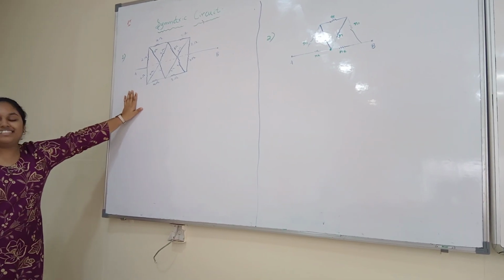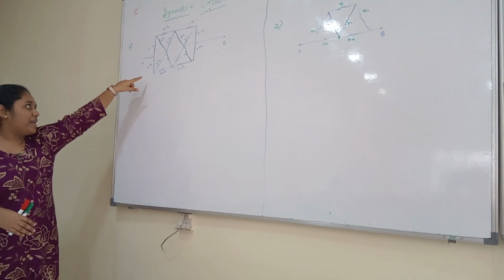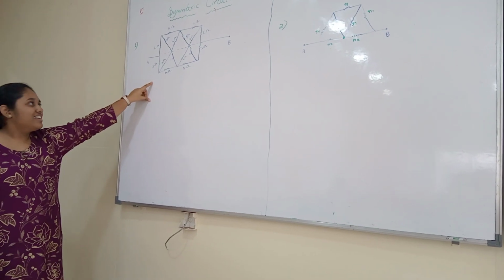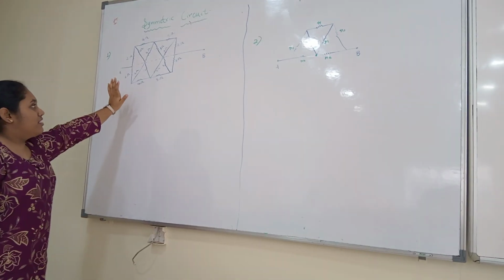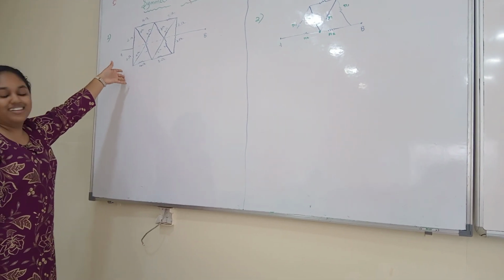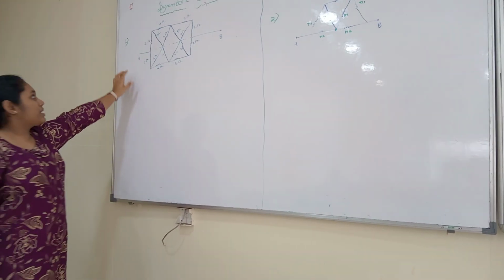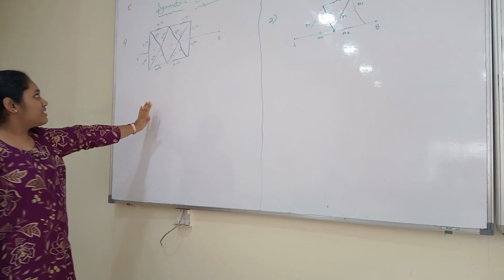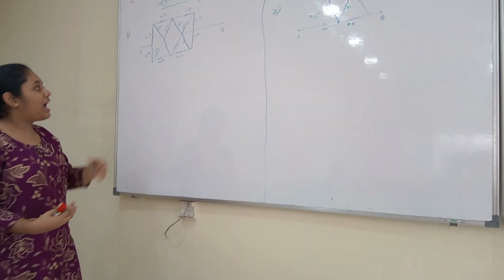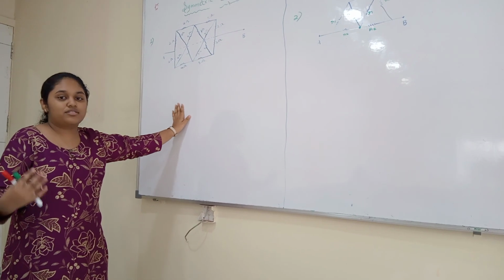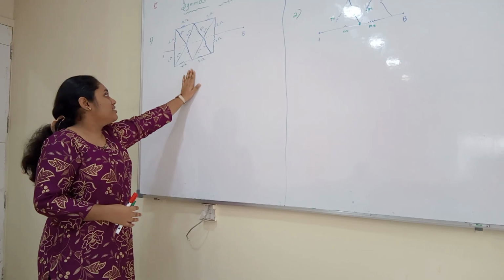Tarun, is there any other technique we have learned that is applicable here? Series-parallel will not work. Naming points and Kirchhoff's law we can do. Kirchhoff's law is available, but to simplify, there is something symmetric here, so we have to look at that symmetry, and that symmetry helps us solve this circuit easily.